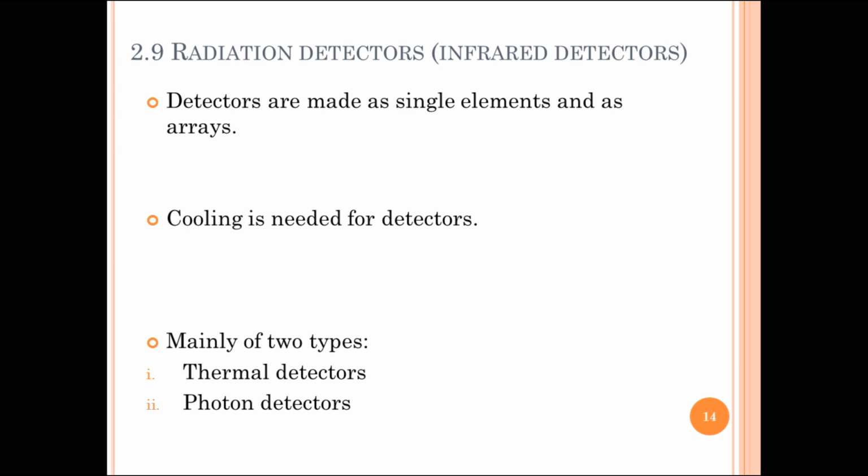Detectors, whether single element or array, may require cooling to reduce electronic noise and increase sensitivity, even though this complication is otherwise undesirable. Cooling schemes include liquid nitrogen dewars, which must be refilled every few hours, thermoelectric coolers or Peltier coolers for no moving parts, or miniature Stirling type mechanical refrigerators.